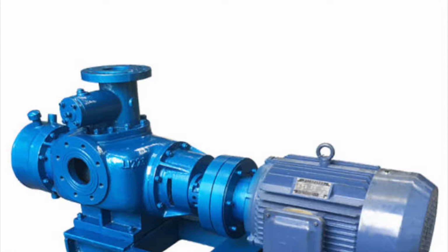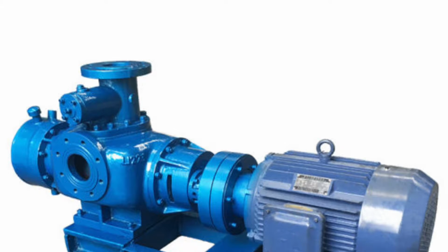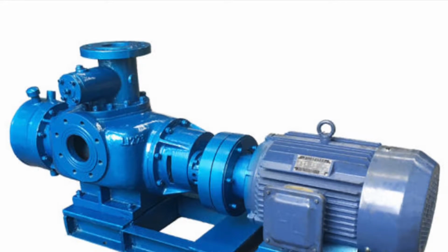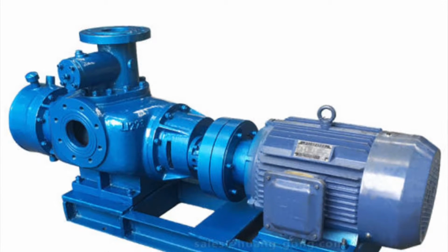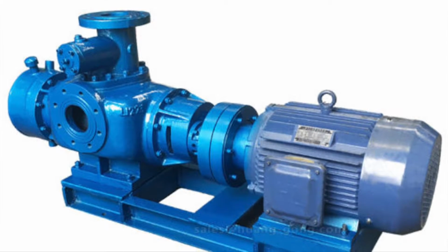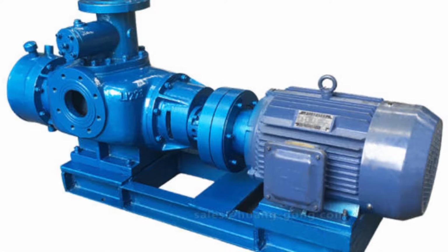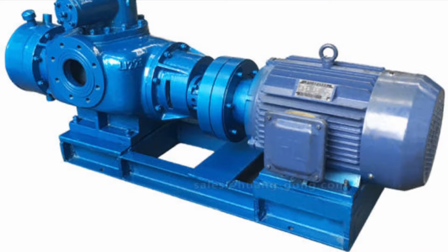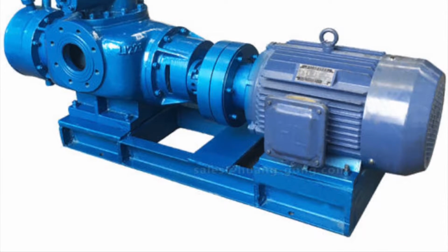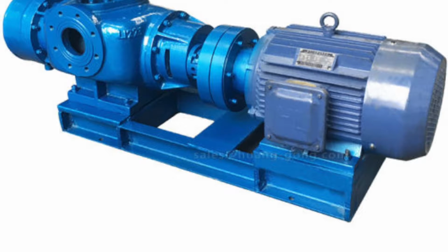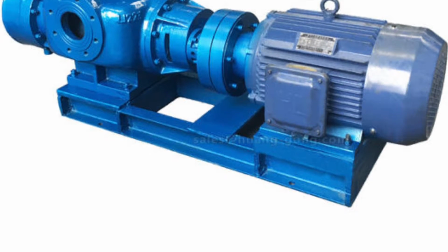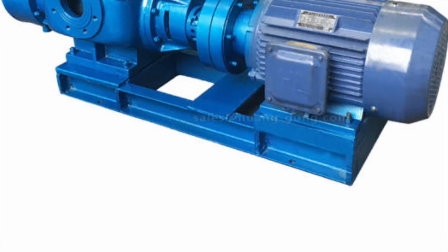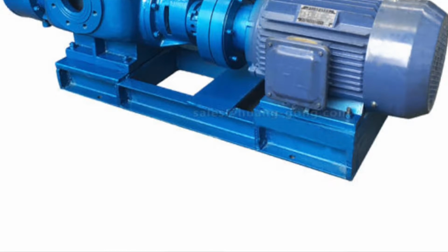So now we're going to start talking about how these positive displacement pumps work and different types of positive displacement pumps. Fluid is drawn into a fixed volume chamber at the inlet and then moved to the outlet by means of either reciprocating or rotary motion that causes pressure. These cycles rely on the pressure that is created mechanically. Positive displacement pumps have consistent flow and work effectively with high viscosity fluids. This is an advantage over centrifugal pumps, whose flow varies according to changing pressure and which can only handle low viscosity fluids.